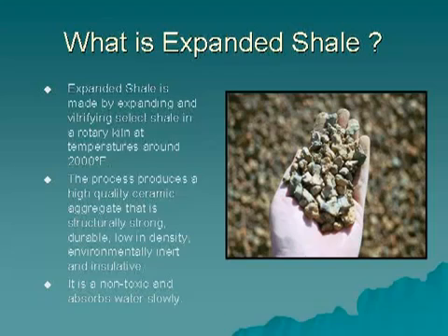Why should it matter to designers and specifiers what type of lightweight aggregate is used to make lightweight concrete block? Since aggregate occupies the most space or volume within concrete, its properties not only impact manufacturing challenges, but its qualities influence the performance of completed concrete masonry over the long term. Expanded shale is considered the gold standard for lightweight aggregate because of its contribution to the lightweight concrete mix design. It is the enabler that makes truly successful structural grade lightweight concrete masonry possible. We'll understand why as we go forward in the presentation.